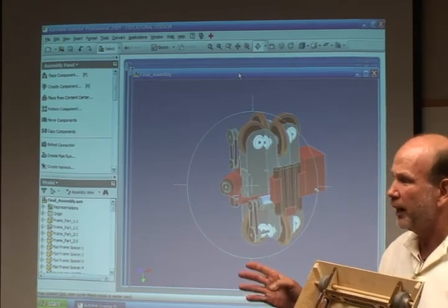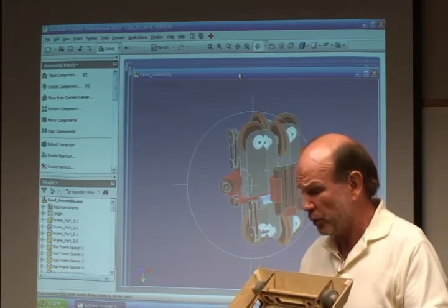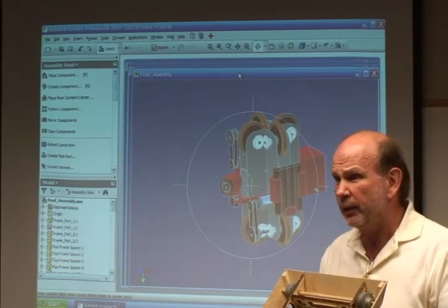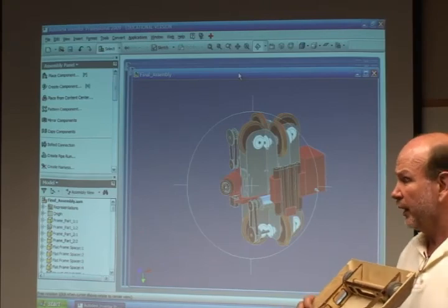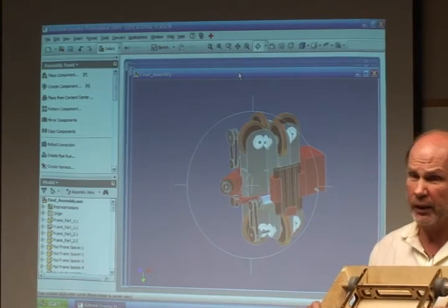You got to keep in mind, when you get down to the final runs, you have somewhere around 15 or 20 minutes to swap out a weapon motor, a drive motor, a belt. So you have to make things accessible so that you can swap these things out real quick. That's something you really have to consider in your design.